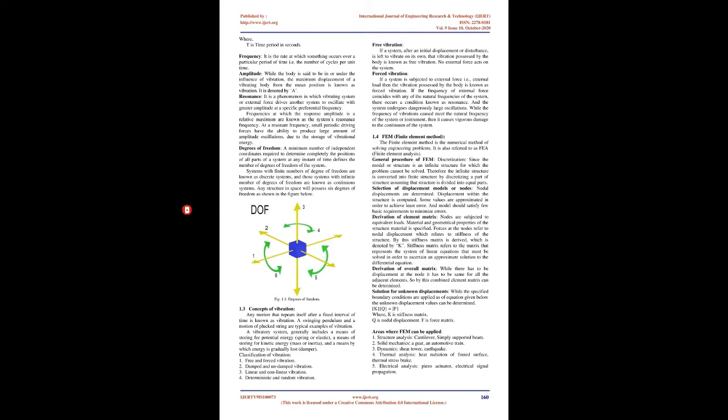Frequencies at which the response amplitude is a relative maximum are known as the system's resonance frequency. At a resonant frequency, small periodic driving forces have the ability to produce large amplitude oscillations, due to the storage of vibrational energy.